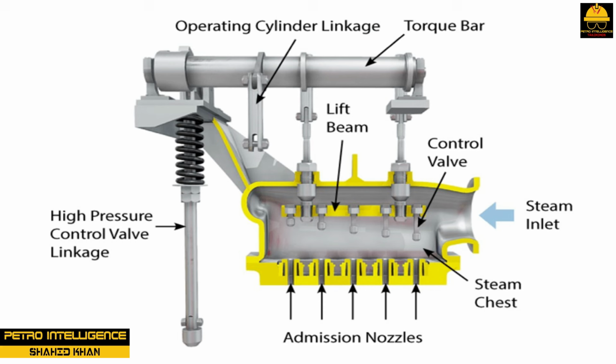Nozzle. The nozzles and nozzle block constitute a precision instrument fabricated from a solid block of high-tensile carbon silicon steel that directs high-velocity steam against the rotor. Nozzle blocks are bolted to the steam chest. The nozzle has overlapping exits that allow the steam jets to converge before being directed against the buckets of the rotor.